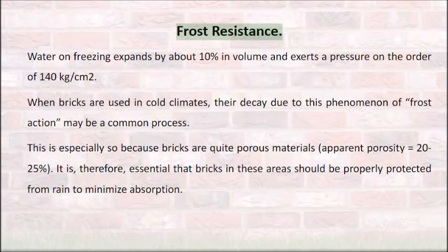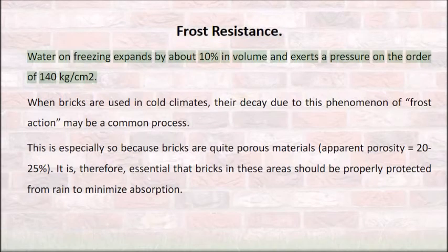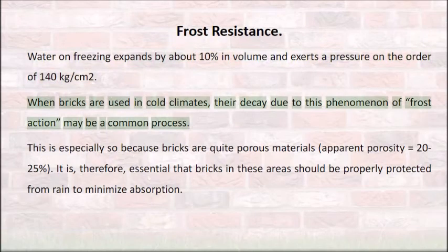Frost resistance. Water on freezing expands by about 10% in volume and exerts a pressure on the order of 140 kg/cm². When bricks are used in cold climates, their decay due to this phenomenon of frost action may be a common process.